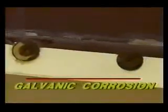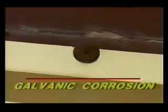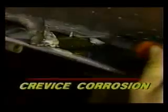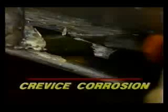Galvanic corrosion results from two different metals being in contact with each other in the presence of an electrolyte, like our steel fasteners and aluminum skin. Concentration cell, or crevice corrosion, occurs in areas where two metals are joined and moisture works its way into the crevice and sets up a corrosion cell.